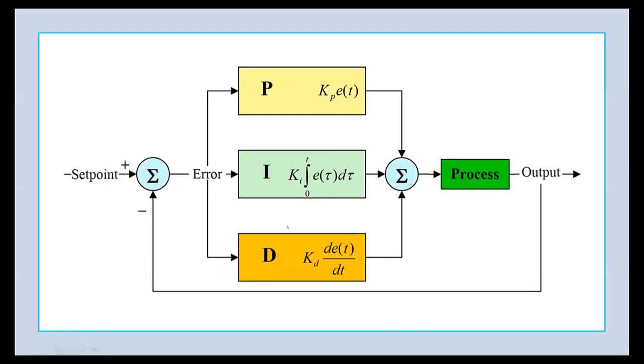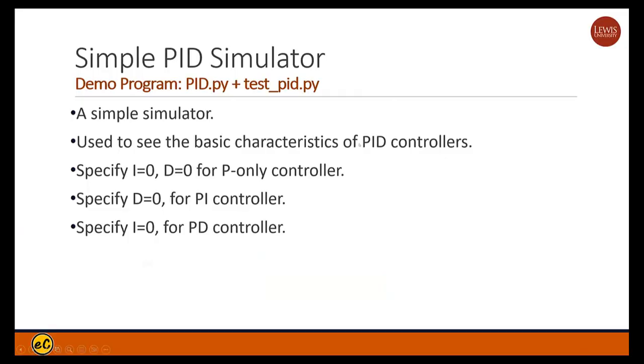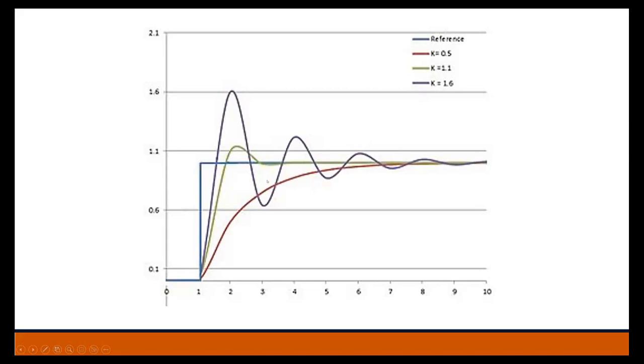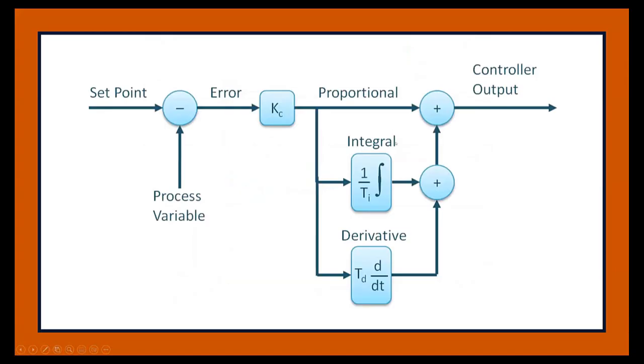You have different K numbers and different parameters, and you will end up with different responses. And there's some damping factor. No damping is no good, but sometimes overshoot or undershoot, if it's well controlled, is okay. A little bit of overshoot or undershoot, by helping the loop reach stability faster, is actually okay. But damping too much may make the system not as comfortable. So it is some sort of trade-off you want to study.